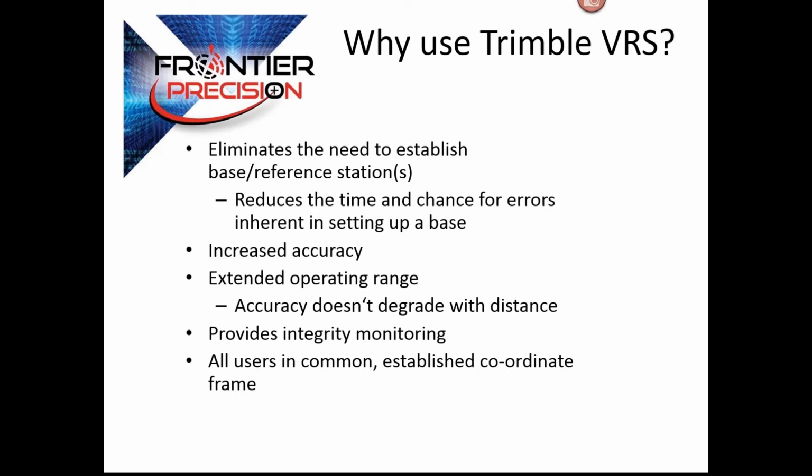And lastly, on that last point, established coordinate frame, one of the major advantages of Trimble VRS, and you'll see this as we move forward, is the ability to broadcast on several different coordinate reference frames, such as NAD83 2011, NAD83 CORS96, or NAD83 1986.